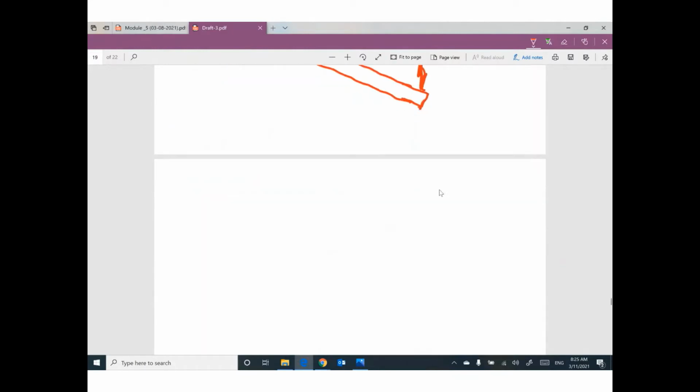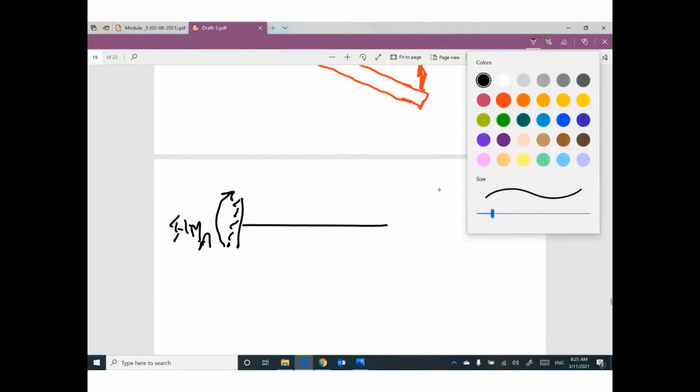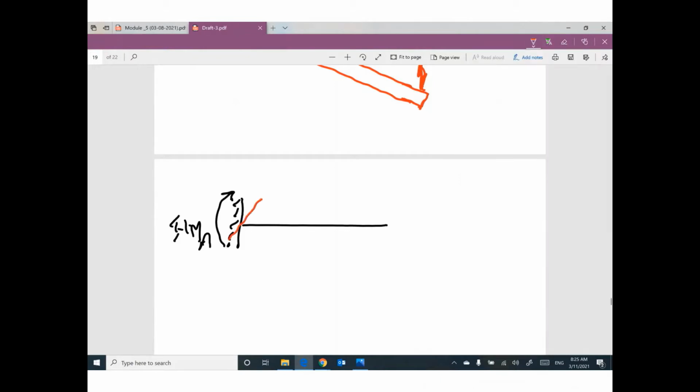If you would like to draw it on a beam, we have fixed like this. So influence line for MA, here is MA. Rotate this fixed by angle theta in the same direction as the moment. In this direction, theta equal 1. So the new shape of the beam will be like this. So this diagram, which is negative, will be influence line for MA.